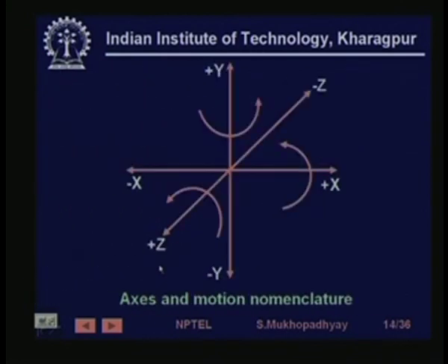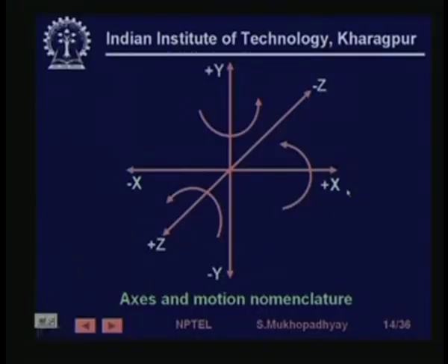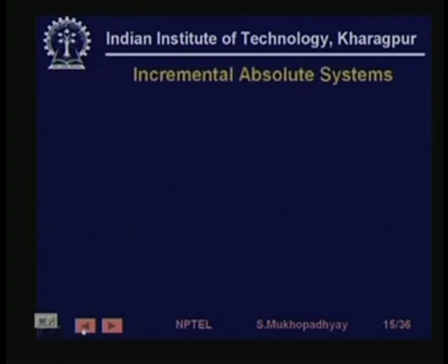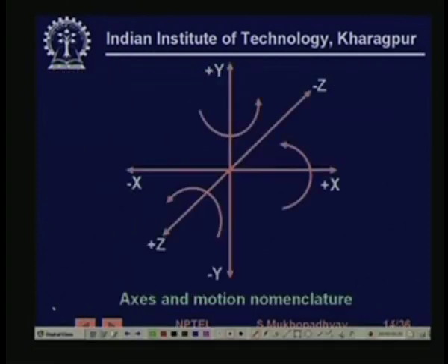It is fundamental to define coordinate systems because most part program instructions, especially the main cutting instructions, all involve various coordinates. The coordinate space is actually very simple. It is like x in this direction, y in this direction, and it is a right-handed coordinate system. Therefore z will be the vertical direction.